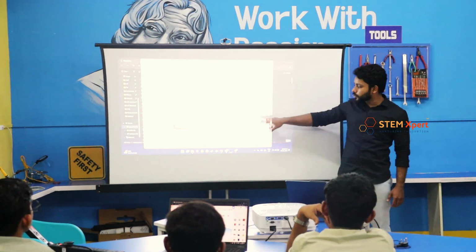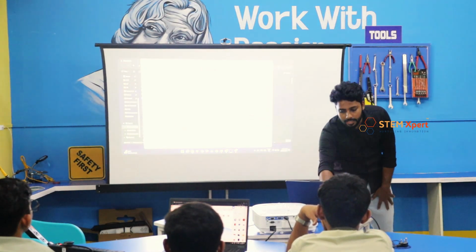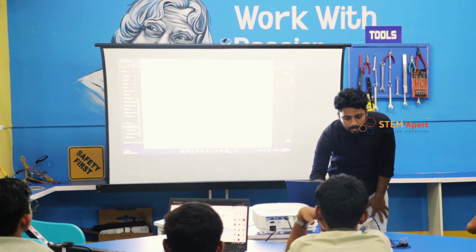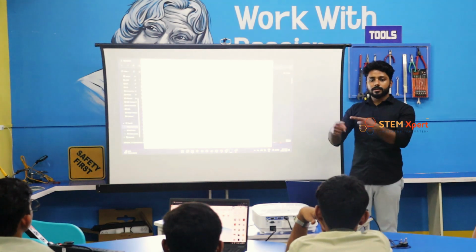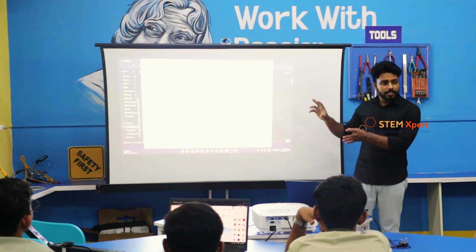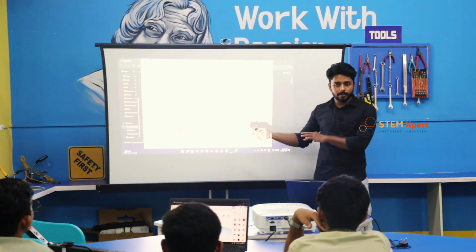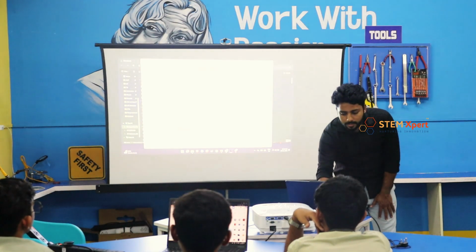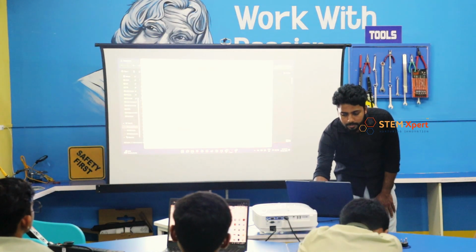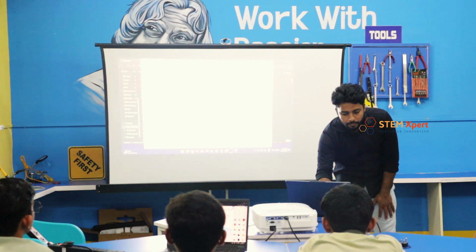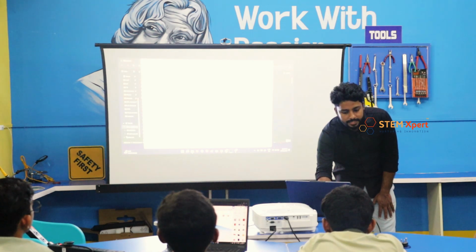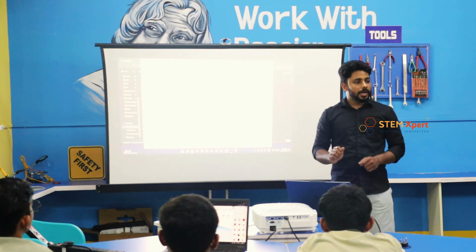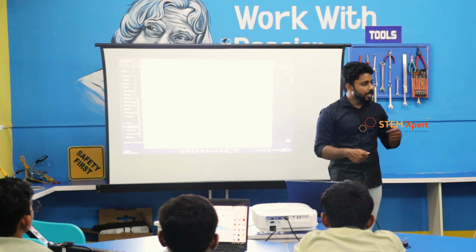If you choose uniform scaling and you change the X dimension, all the axes will be changed accordingly. Understood? Now we are using 40 mm in size, so here we will be changing the dimensions to 40 mm. Now it has changed to 40 mm. This is the file that we are using, and we are going to convert it into a printable format.